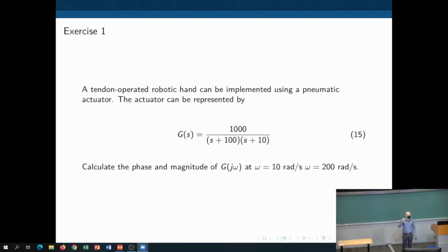expand and contract. And through this, we can determine the maximum, for example, if this transfer function corresponds to the ratio between the input and output, let's say a voltage input and a position output of the actuator, that will tell us how fast the actuator, when put in a robotic hand, can actually grab something and release it, how fast it can move.